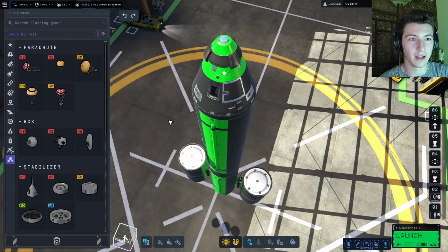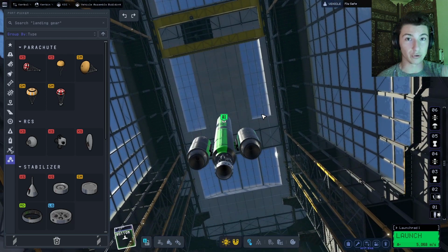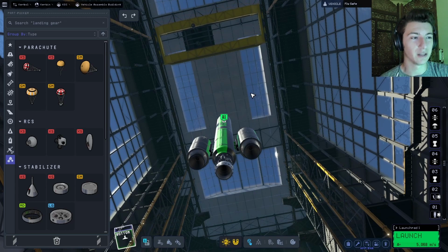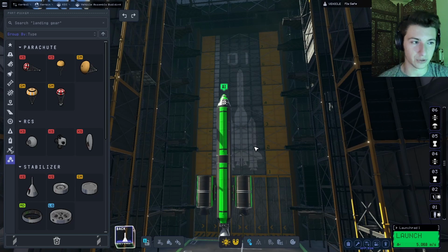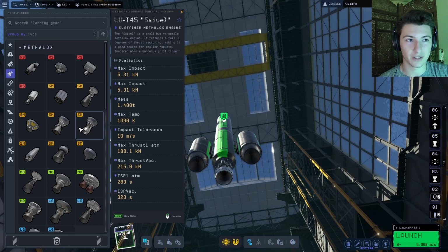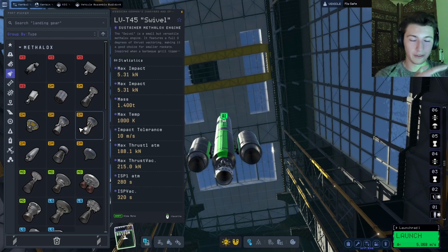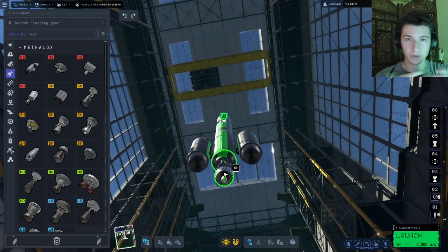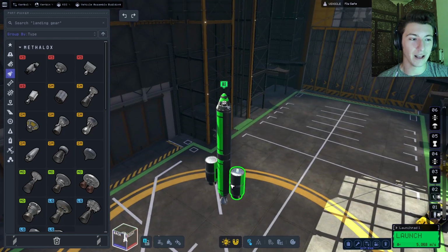One of the things that will happen is when you are driving, quote unquote, your spaceship into orbit, you're going to need to adjust its heading. You're going to need to rotate it in all sorts of different directions. There's a couple ways that you can do this. For one thing, if we look at our engines, some of the engines, such as this one, have a gimbal, which means the actual cone of the engine, this bit, can be rotated to different angles to provide thrust at different angles. That relies on using your fuel, so there are some alternatives.